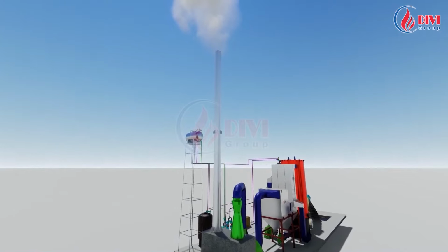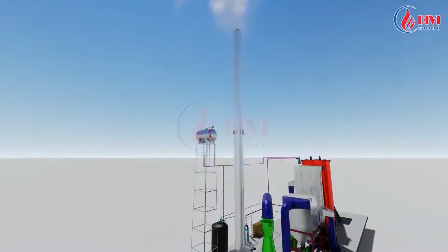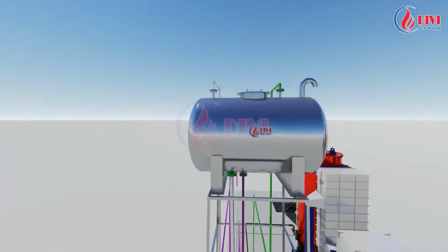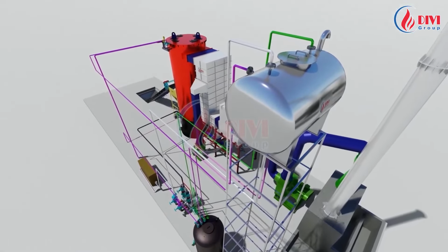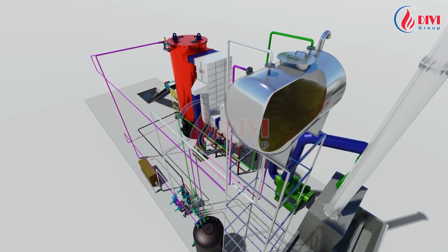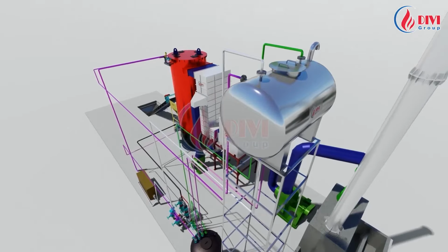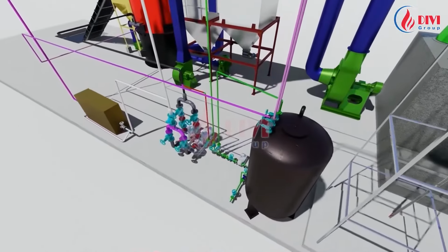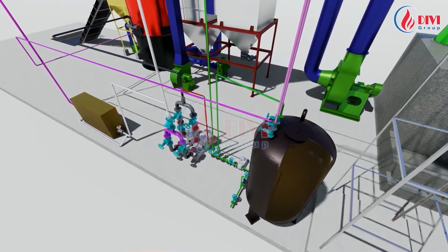Next, we will learn about the main oil system of the thermal oil heater. This is the expansion oil tank. This oil tank is placed higher than the thermal oil heater body. In case the oil heats up and expands in volume, the expanding oil will be pushed back into this oil tank. When there is a shortage of oil in the system, the oil in this tank will automatically fill in the system. This is a backup oil tank to add to the system when the oil in the expansion tank runs out, or is a place to store the oil when the oil in the expansion tank is full.